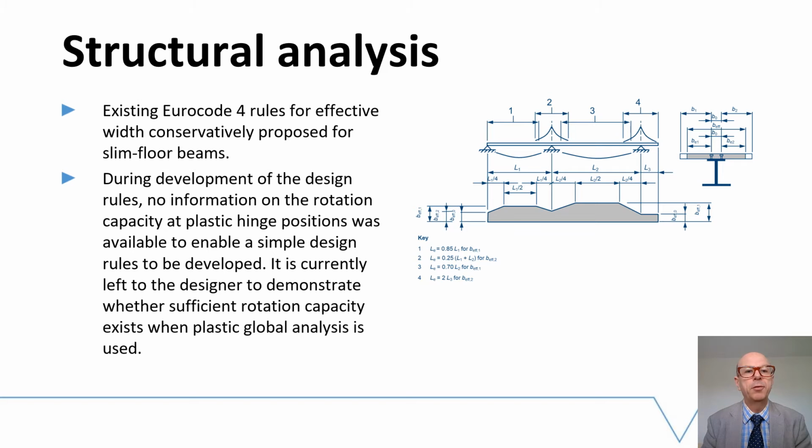Also, during the development of the design rules, no information on the rotation capacity at plastic hinge positions was able to be found to enable a simple design rule to be developed. Therefore, it's currently left to the designer to demonstrate whether sufficient rotation capacity exists when plastic global analysis is used, and to remedy this situation, future research is needed.